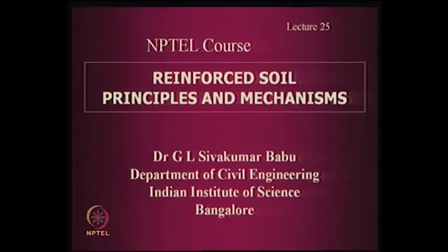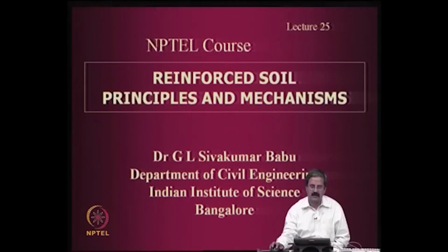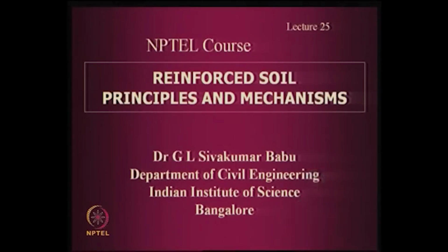In this lecture, we will be talking about reinforced soil, its principles and mechanisms. As I just mentioned, in ground improvement, we have the use of inclusions. Inclusions means, for example, a steel rod or anything that can be introduced to give a reinforcement effect that helps in increasing the bearing capacity, reducing the settlements and increasing stability.